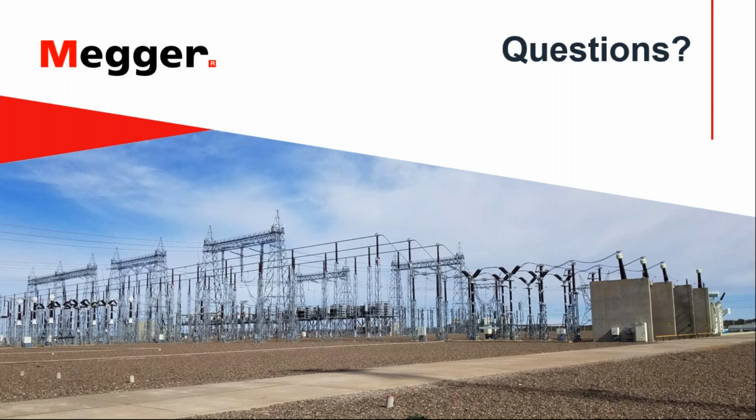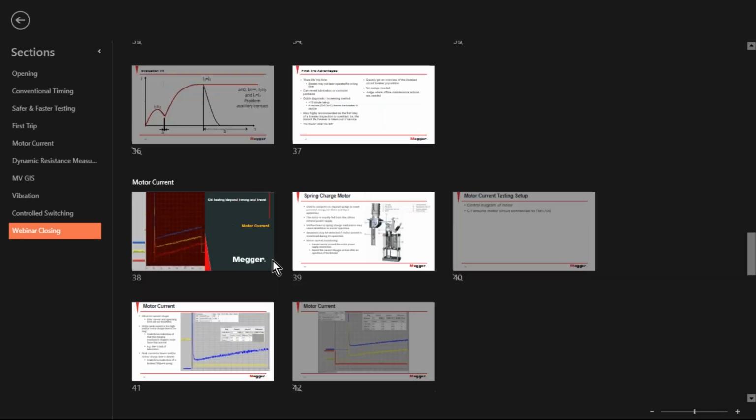All right, thank you, Volney. We have time for one last question, and I'm going to direct that over to Daniel. Daniel, is it possible to test SRM or DRM with both sides grounded? If yes, how accurate is it compared to one side grounded? Yes, you can use this method with both sides grounded. And how accurate, and would you need an extra accessory like a CT? I think Volney showed a slide on using this technique to test the contact resistance on a GIS breaker.